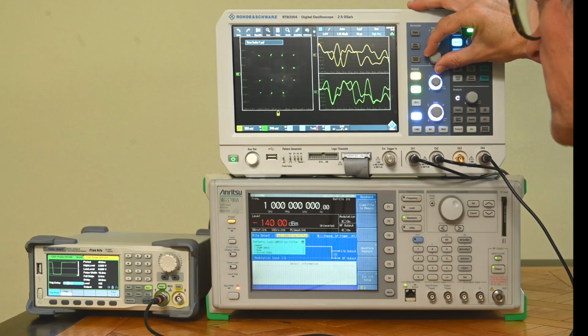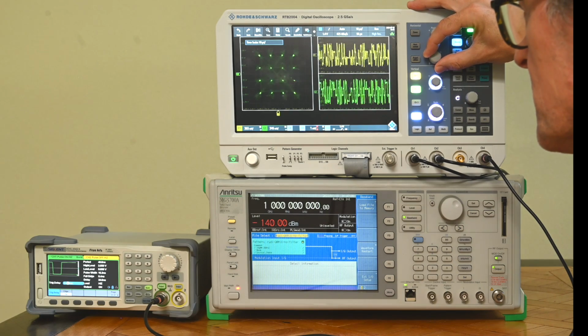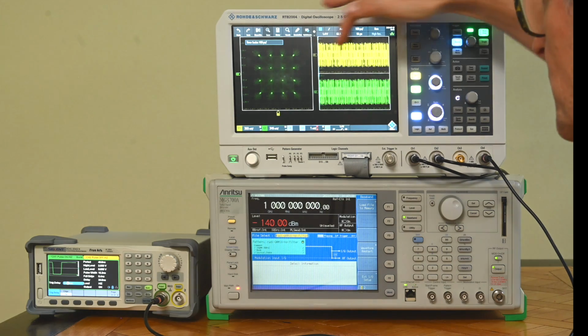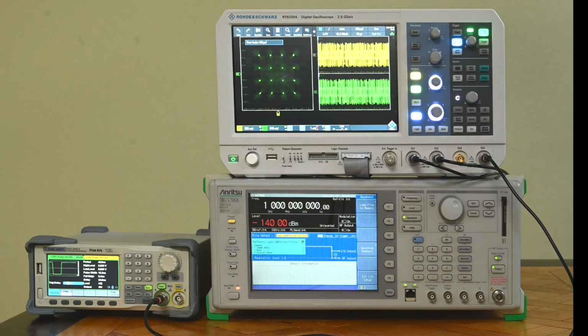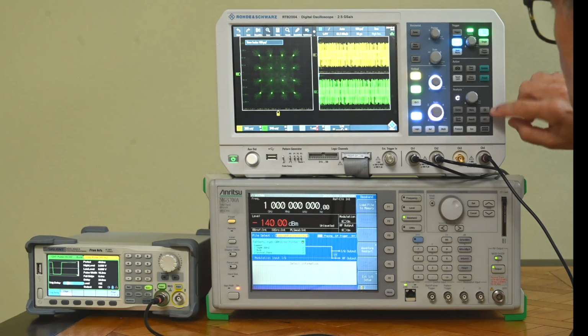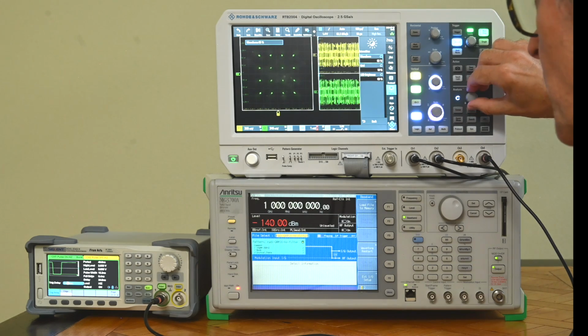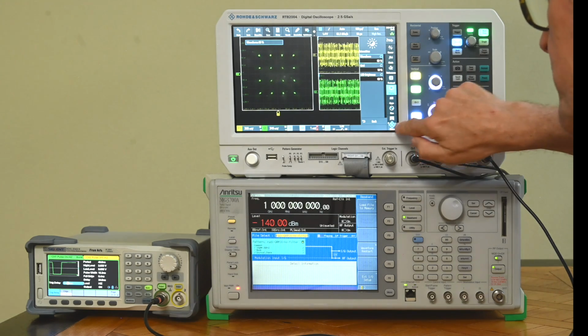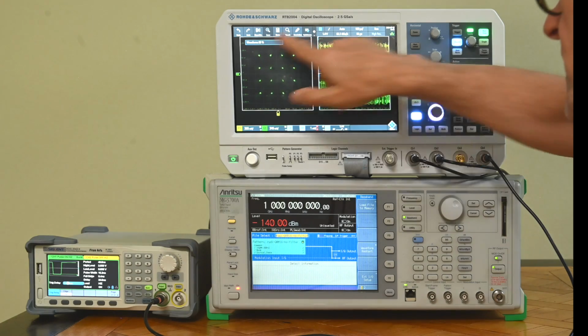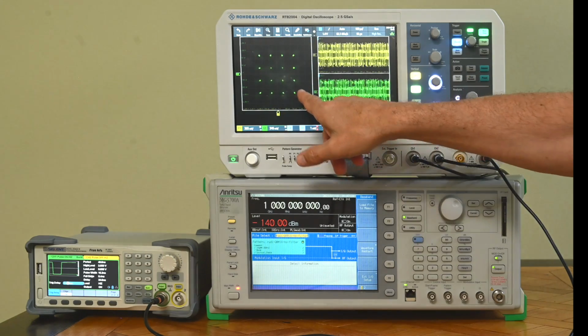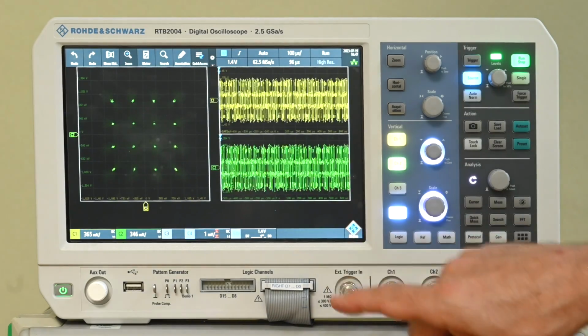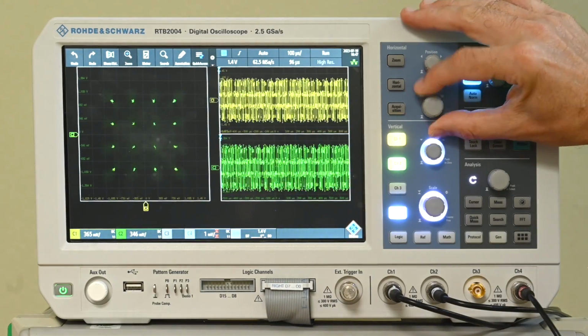Here we see the signal jumping from one position to the other. When I increase the time here, so I'm capturing more periods, I quite clearly see the diagram coming in. Let me put the background waveform a little bit lower. Now here we can observe the constellation points. Now we're zoomed in a little bit more, and again we can see the constellation points.